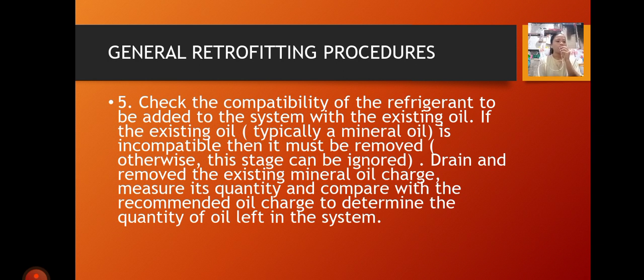Since many small hermetic compressors do not have oil drains, removal of the compressor from the system may be necessary for draining the lubricant. The best point in the system to drain the lubricant is the suction line of the compressor. Small hand-operated pumps are available which permit the insertion of a tube into the compressor access port.